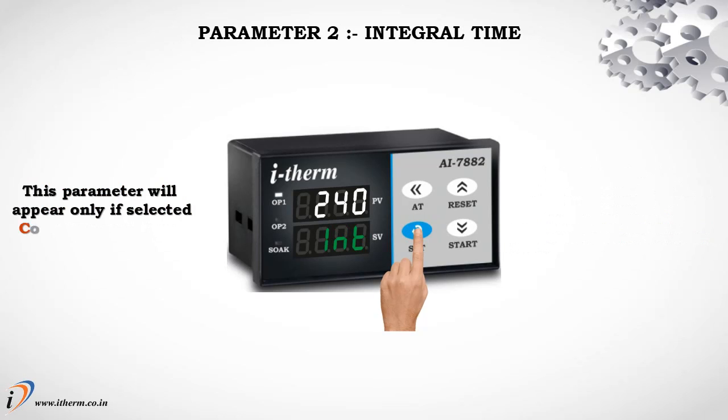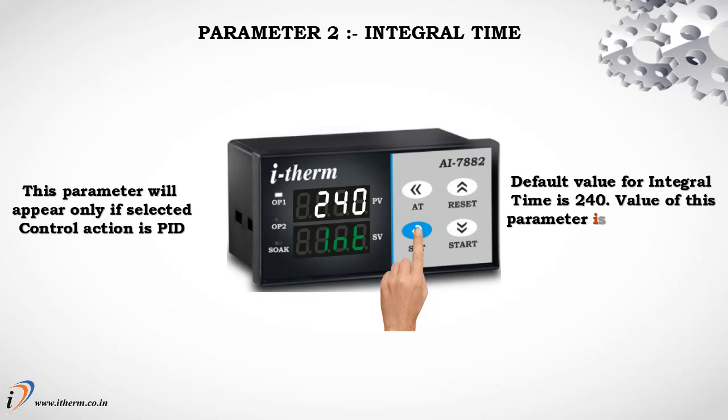Parameter 2, Integral Time. This parameter will appear only if the selected control action is PID. The default value for integral time is 240. The value of this parameter is automatically set by the auto-tune function.